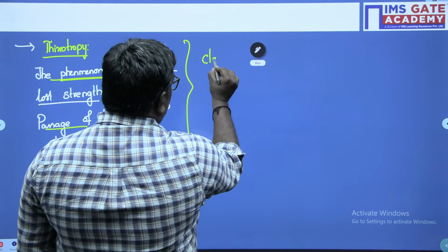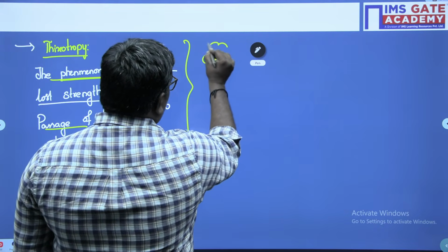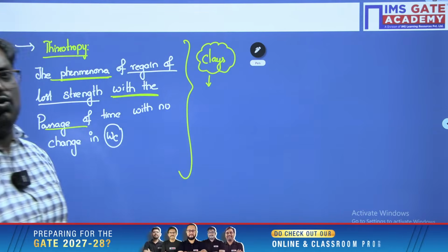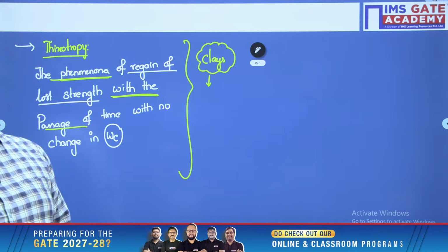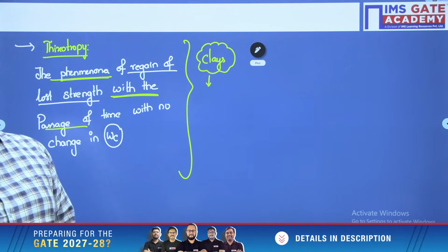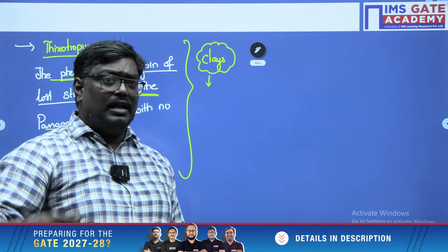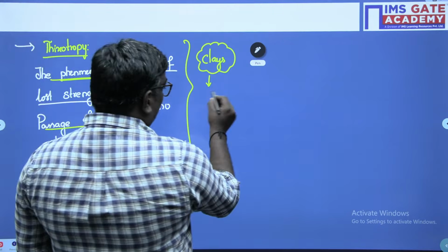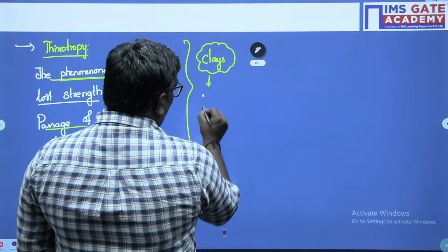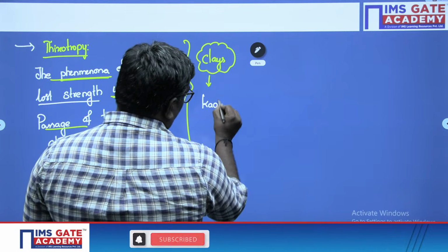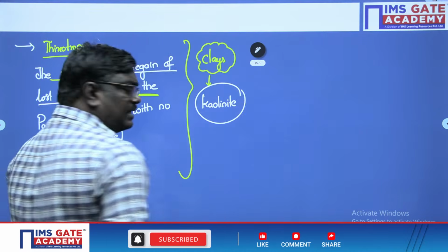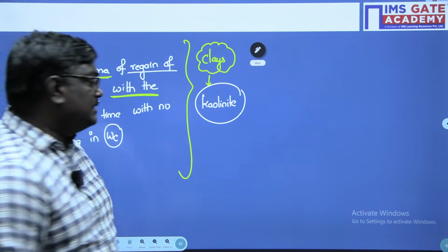Similarly, in coarse grain, quartz, feldspar, and some mica will be present in gravel and sand. In clays, we have different clay mineralogies, sir. First one we have is kaolinite. Remember, it contains some gibbsite and silica.